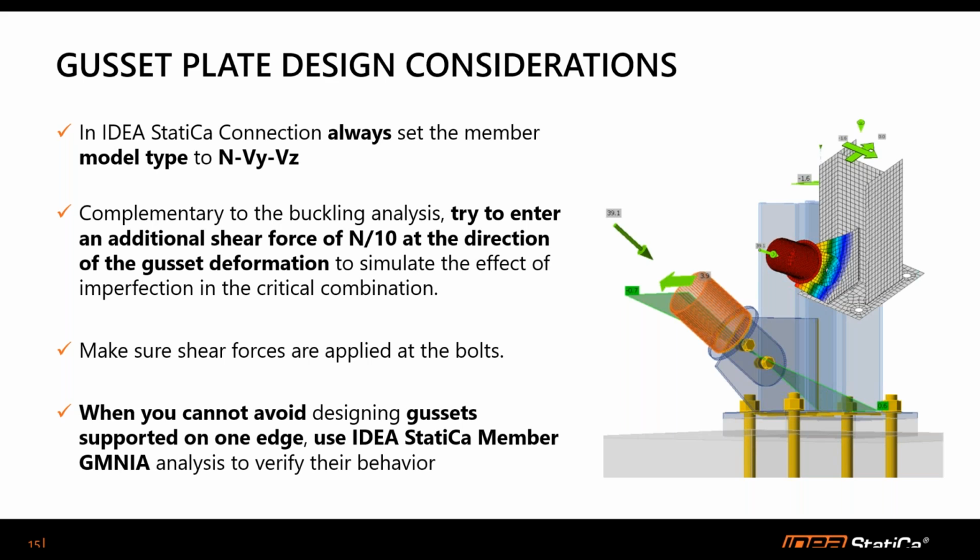One last thing is that when we cannot avoid designing gussets supported on one edge, which seems to be the case as many designers are forced to design this configuration, please use IDEA StatiCa Member GMNIA analysis to verify the behavior of the overall bracing system.